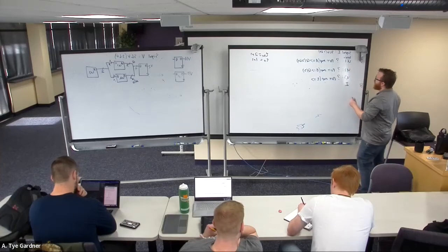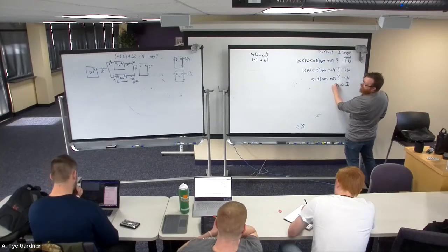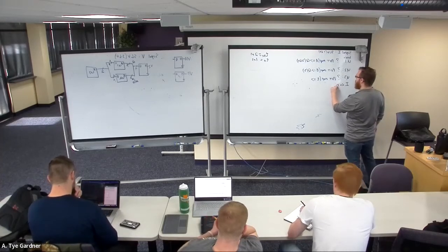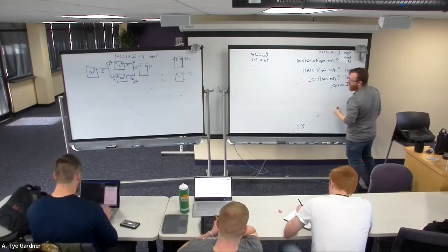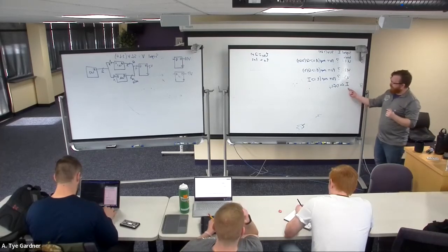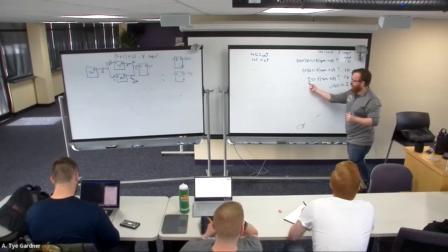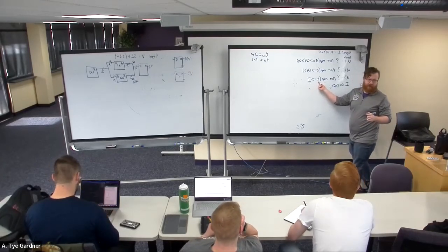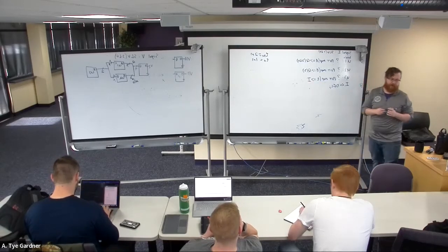So I come down here, I say, well, I now is D and C? And E gets mapped to I. Subtle difference, right? I had to create an intermediate signal that was the concatenation. This is 2 bits. Now I can plug the 2-bit I and the 2-bit E. I cannot concatenate at the port. I have to do it at a signal.